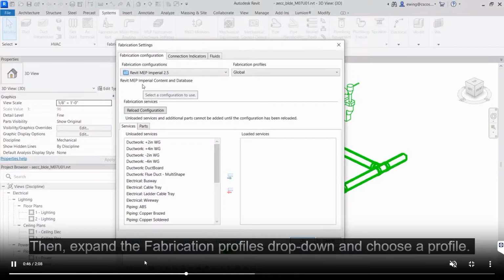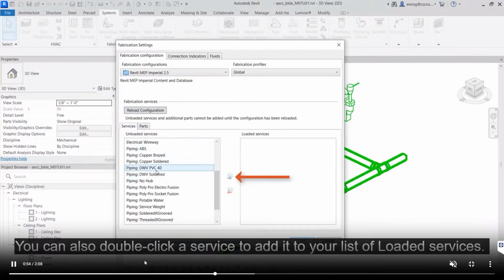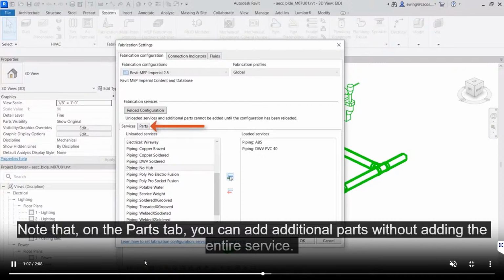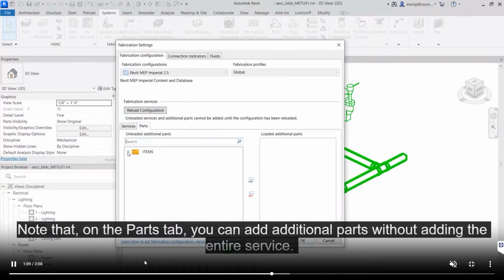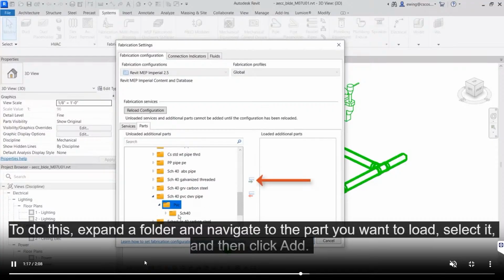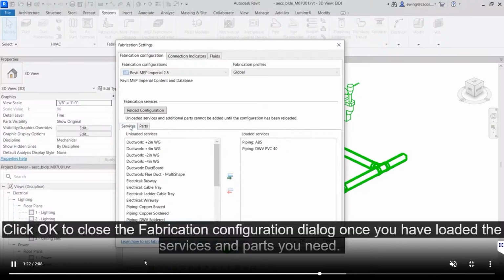For those of you who don't know Revit, you've got these generic sort of pipes, generic ducts with typical sizes, and then the fabrication parts, what they do is they interface with fabrication software, and this fabrication software can read the schedules that you're exporting from Revit, and based on the sizes on those schedules, on those components, they share a database, fabrication CAD MEP, and then you can actually spool them onto the devices.